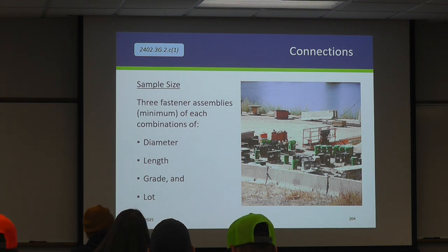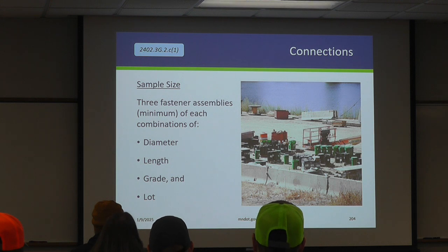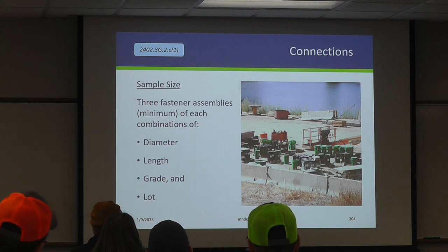You have to do 3 for every 2.5 inch, 3 inch, 5 inch, 9 inch. So on the Twin Ports job, where a lot of these pictures have been coming from, I think the first bridge, we had 10 individual combinations of bolts. So that was 30 bolts that had to be tested. So you can see how much time this could take, right? So it's important to make those separations.